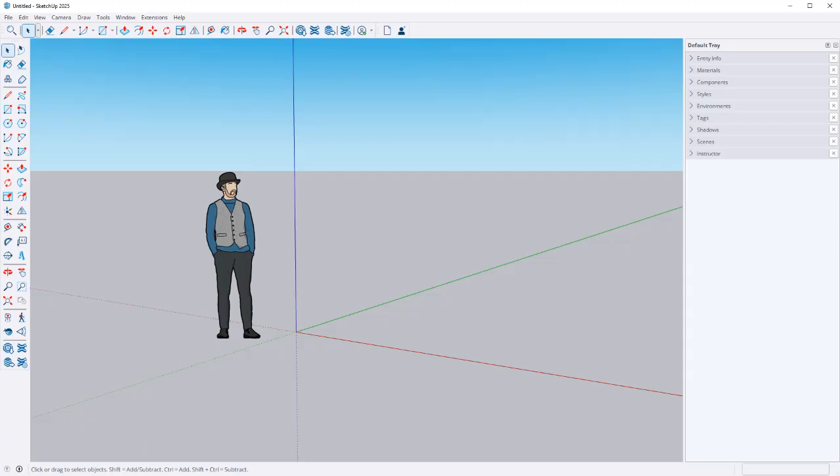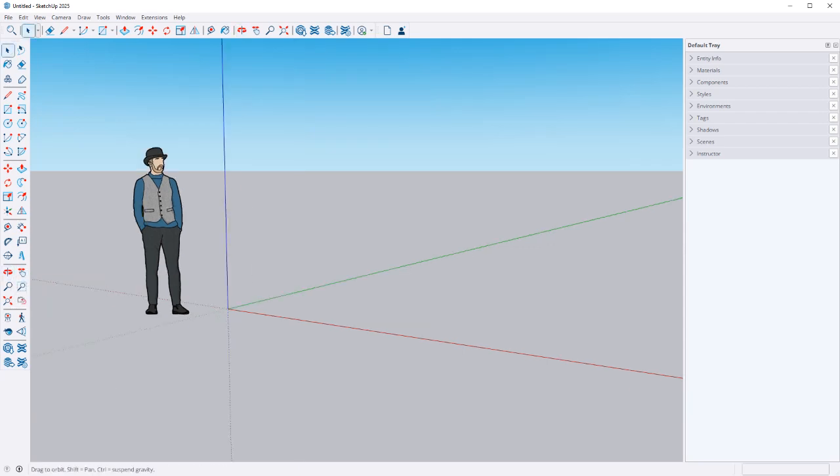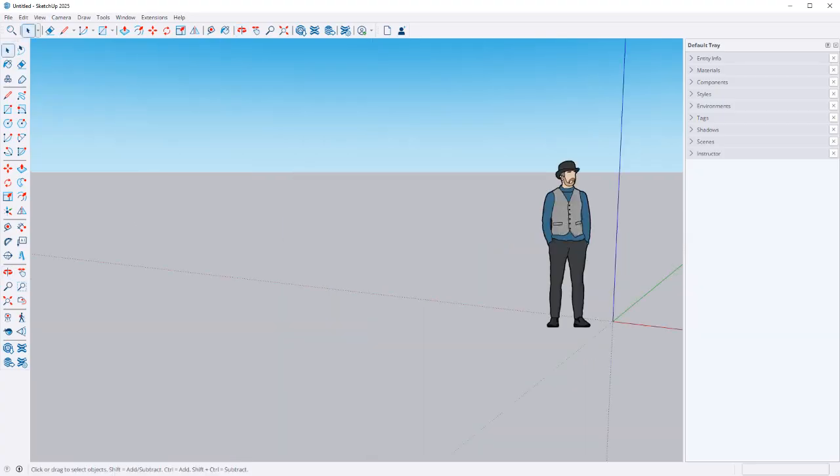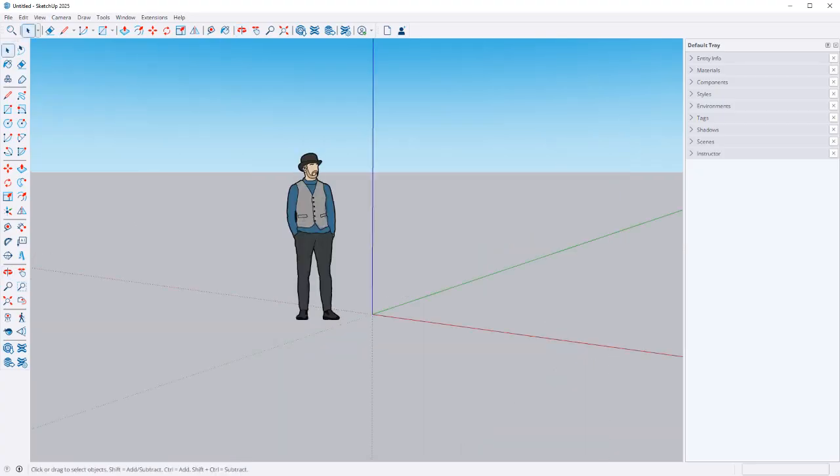There's two main ways that we're going to get around in here. The first one is using the middle mouse button. If you press down and hold on the middle mouse button, you can see that it gives me the sign for the orbit tool, which is this one right here. Anytime I press it, it's going to toggle that tool on and then go back to the one I was last using. You can also double click with it and it will jump you sideways to get somewhere too.